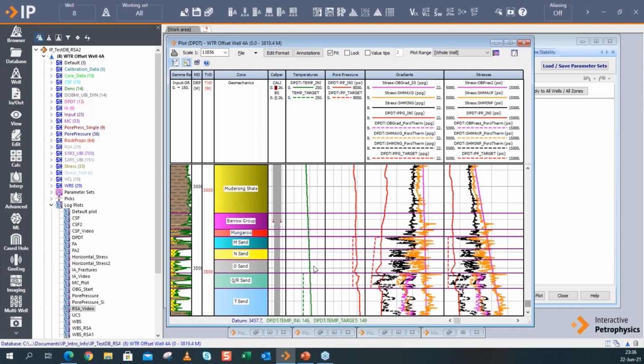And the same is done with different temperatures. Imagine that maybe in the lower two sands here, we want to inject cooler liquids. So this solid green line is a temperature gradient, and the dashed green line is a lower temperature. So there is a delta temperature which affects also the in situ stresses. Now, calculations can be very simple in terms of a single stress path factor which is adopted, but you can also go more complex and account for the different elastic properties of the rocks.